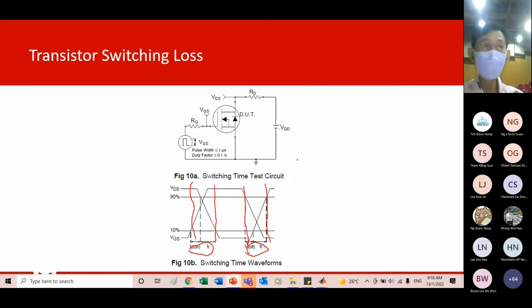Does size matter? If size matters, you need to use high frequency. And consider the power of your converter. Of course, with higher power, let's say 1% loss is a lot compared to, let's say, 1000 watts of power. 1% loss of 1000 is a lot. But if you're like our charger, 33 watt or 35 watt, now they call it fast charger, 1% loss is nothing. So like I said, this is part of the design thinking that you need to consider first.